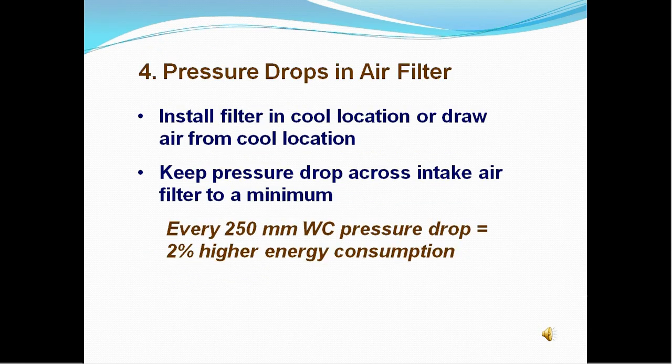A compressor intake air filter should be installed in, or have air brought to it from, a clean, cool location. The better the filtration at the compressor inlet, the lower the maintenance at the compressor. However, the pressure drop across the intake air filter should be kept to a minimum. The pressure drop across a new inlet filter should not exceed 3 pounds per square inch. As a general rule, for every 250 mm WC pressure drop increase across the suction path, due to choked filters etc., the compressor power consumption increases by about 2% for the same output.